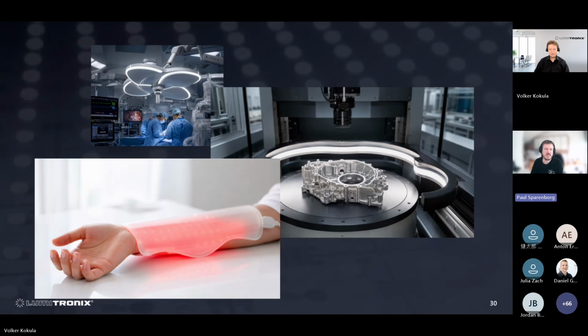We see such applications especially in medical lighting, but also in optical visioning systems and in applications which are very close to the human body. In many of these applications, we need a lot of light, we create a lot of heat, maybe also because LEDs might not yet be as efficient, especially in the area of UV and UVC technology. And it is greatly beneficial to be able to create a 3D bendable PCB, which can still sustain very good thermal management.